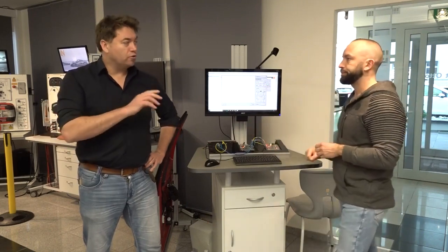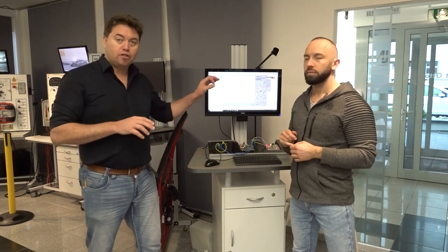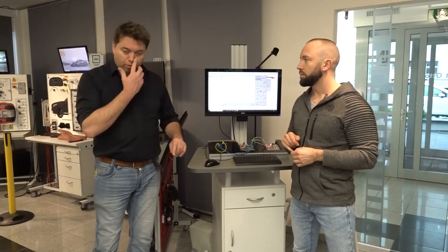It's also worth noting, talking about when you go to the vehicle and try to diagnose a problem, I know, for example, a lot of people say with Volkswagen, you just disconnect the node and you can see quite easily, does the oscilloscope change? You can see if that node or somewhere before or after that node is causing the problems. But not every vehicle has that capability. There's something called termination resistors. There are resistors in the system that allow it to basically be in a loop. And they can sometimes be found within the control unit, sometimes within the wiring harness.